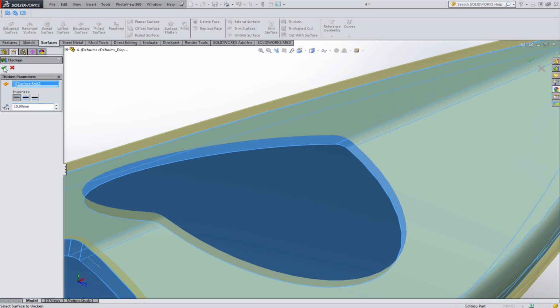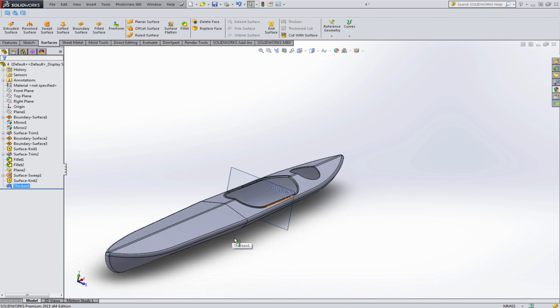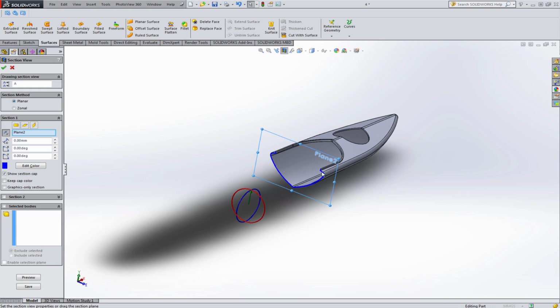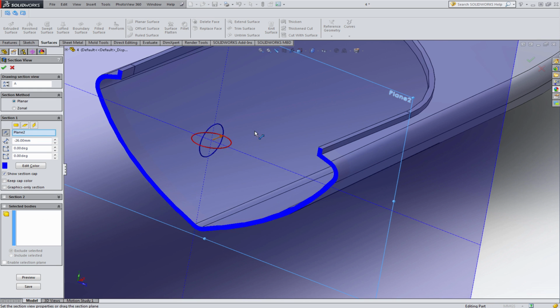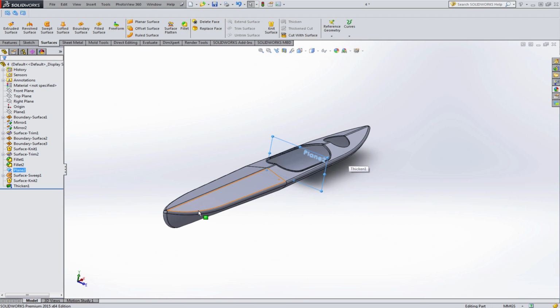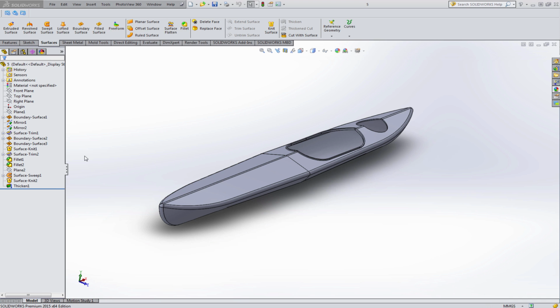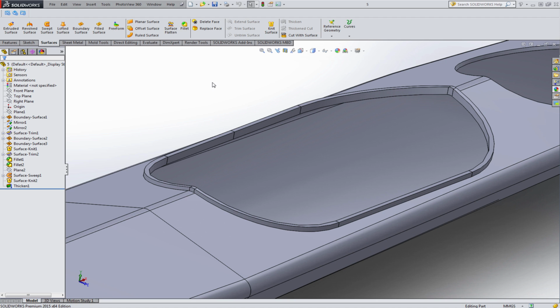If you have not used the same dimensions as I did, it is possible that this option will not do what we would like. Please note that we no longer have surfaces in the feature tree. Now this is a solid body. Now I'm going to round the edges by using a fillet option.